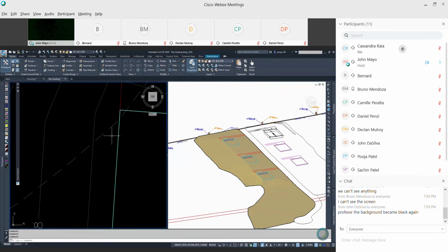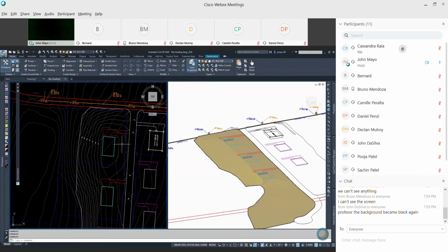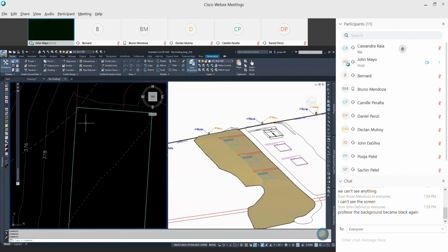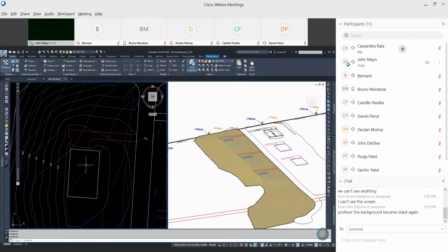All right, and I don't want to lower the building below the road because then I'm going to need sump pumps. So I'm going to try the best I can to keep all these first floors a minimum of 2 feet above the road, just so I can get a gravity sewer connection out there, and I don't need sewage pumps in each house.